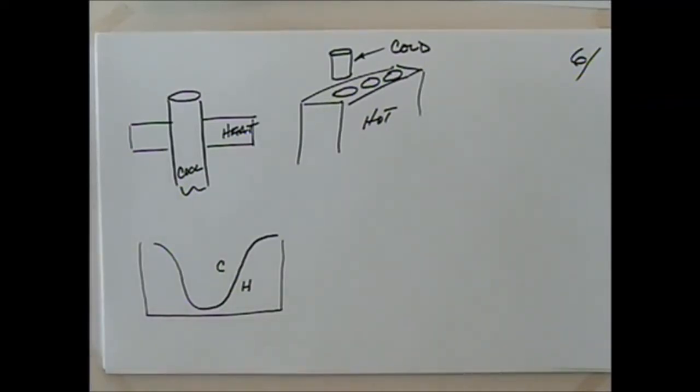After 75 years of satisfactory service, the bell cracked probably as a result of fatigue from superimposed vibratory stresses caused by ringing the bell. Attempts were made to arrest the crack growth by drilling holes at the ends of the crack, and further crack extensions subsequently occurred. And your author cites this as proof that residual stresses are still present in the bell, which is kind of cool to think that the stresses that were in that bell in 1752 or 1753 are still actually there.